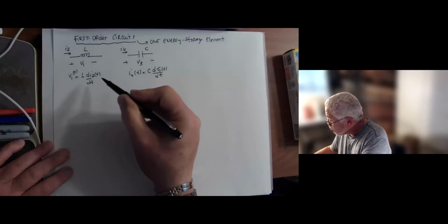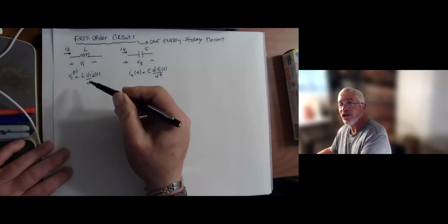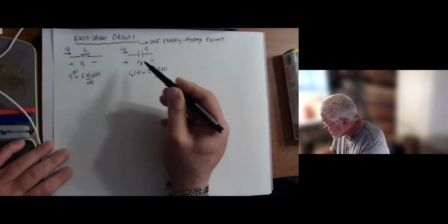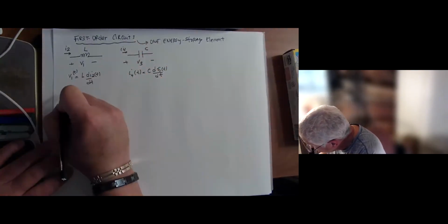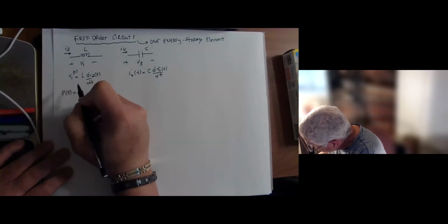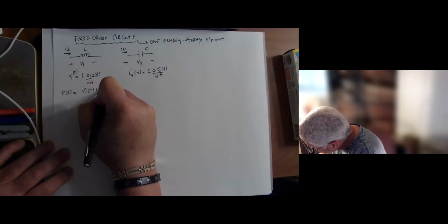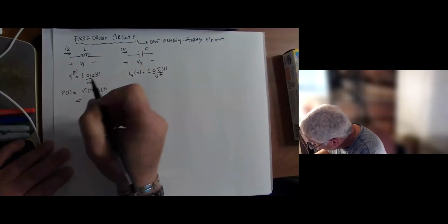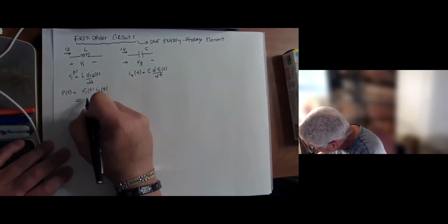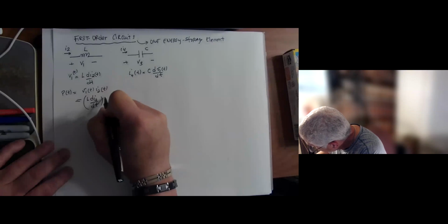This is what's going to bring the differential equation relationship into our nodal and mesh analysis when we have these elements in there. Also important, we talk about power, instantaneous power, essentially voltage V1 of t times current I2 of t. And if we put this, we're essentially looking at L di2/dt times I2.